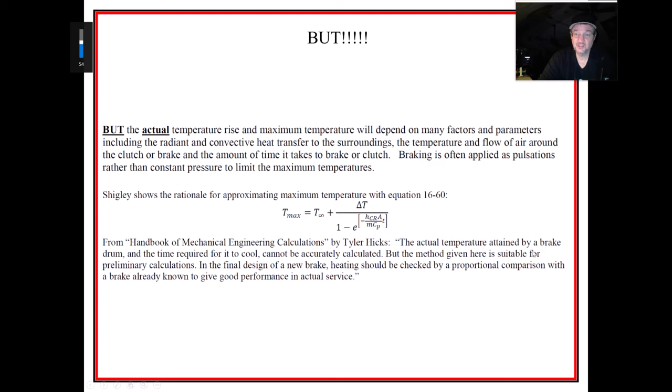But the actual temperature attained by a brake drum and the time required for it to cool cannot be accurately applied. We can end a period right there. Just make that statement. But the method here is suitable for preliminary calculations. In the final design of a new brake, heating should be checked by a proportional comparison with a brake already known to give good performance in actual service. So you need experience to be able to actually design with this.